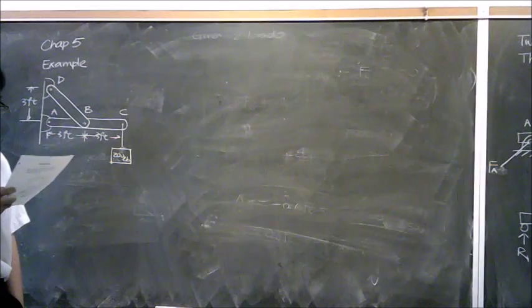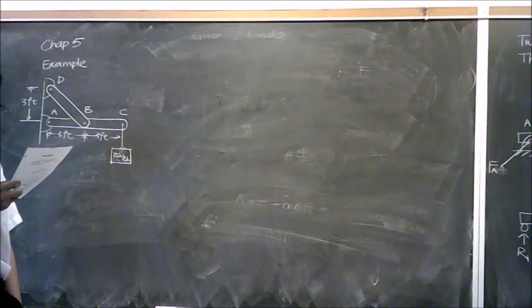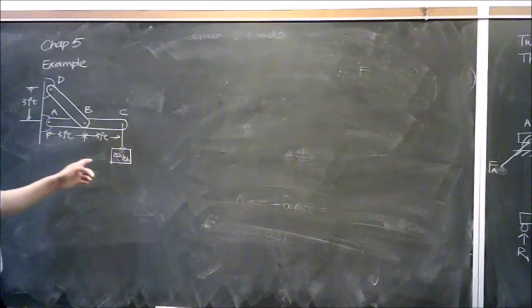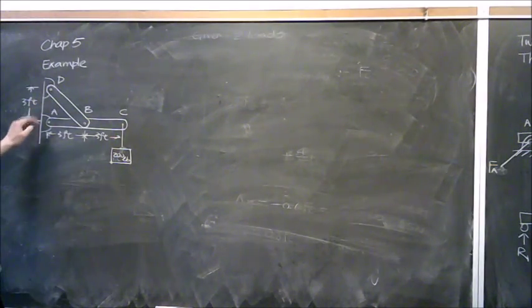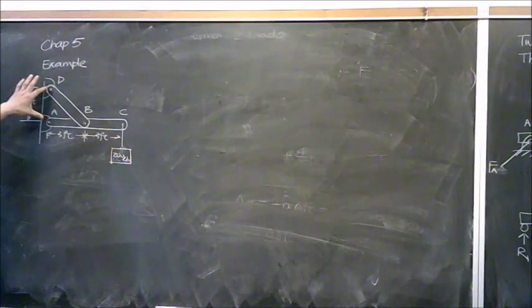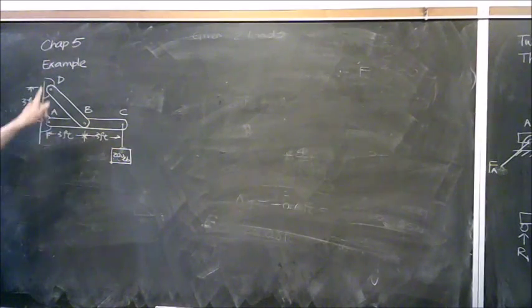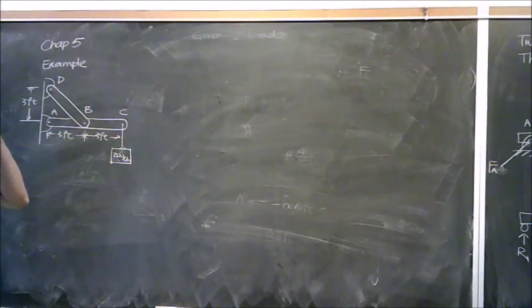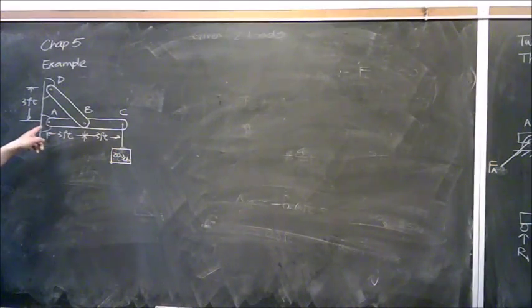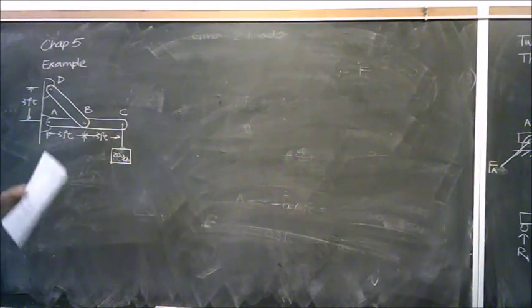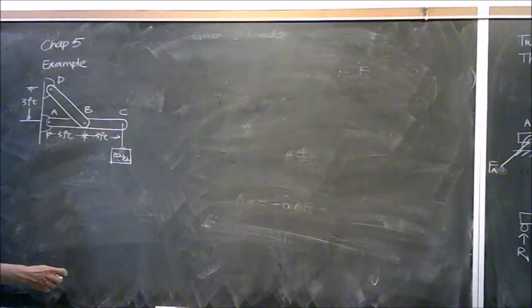Okay. You can use the regular configuration: Fx, Fy, Fx, Fy, the 4 forces located at A and B, and try to solve for the unknowns. That will work because it's not really difficult to deal with those kinds of things if you decouple everything and understand what's going on over here. But I would like to use the 3-force member method to solve the problem. So why do I say it's a 3-force member?